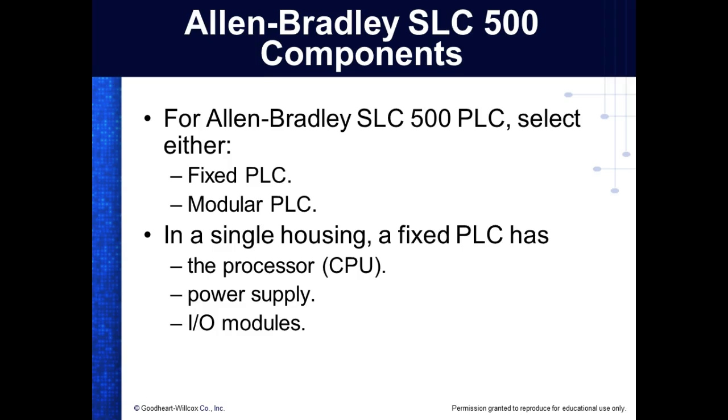Allen Bradley, we're going to look at the 504. This is a modular PLC. Everybody understand modular? So modular PLCs in the old days came with something that we call a rack. And this is what we call a 7-slot rack. You know, 1, 2, 3, 4, 5, 6, 7-slot rack. And then in the back of it, we have what we call a backplane. And what's nice about these guys is that you figure out what you want.